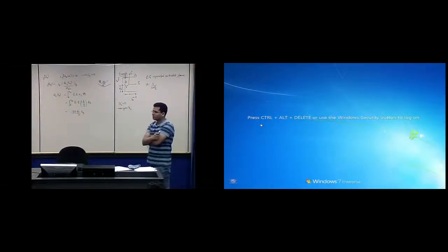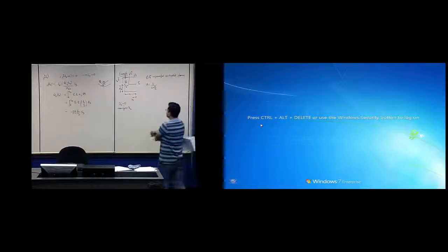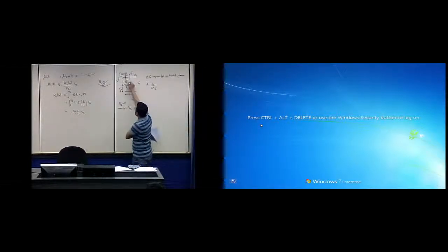Yes, exactly. So the values will change based on the S coordinate, and generally the shear flow keeps going because the shear stress has nowhere to flow. So it will be the same. If you are considering the direction of this S2 such that it goes away from that edge, then it will be the same. But if it's converging into that section, then your conditions will change.